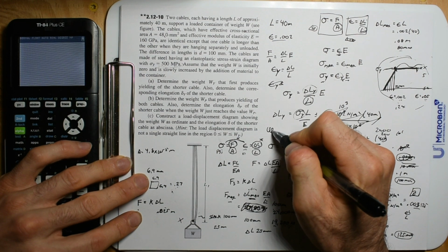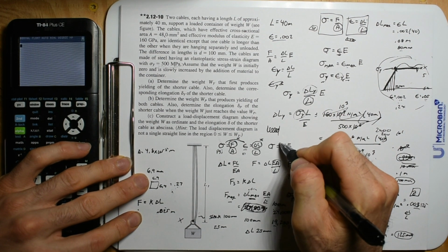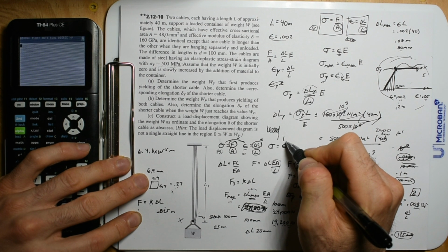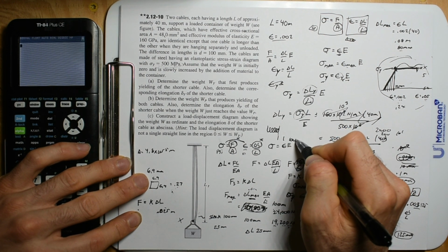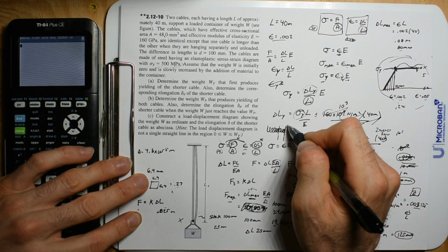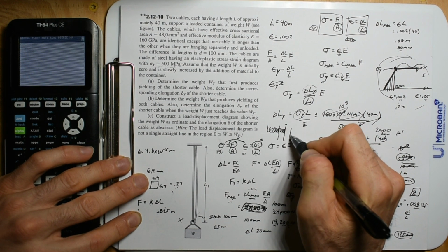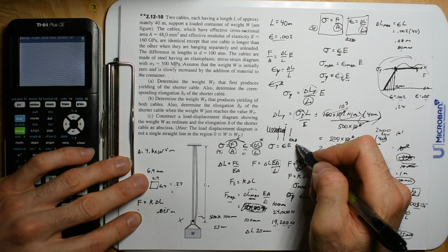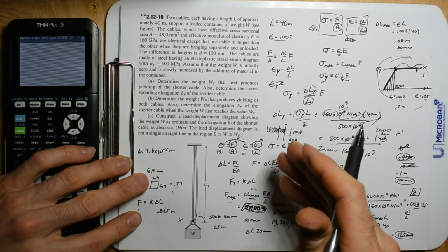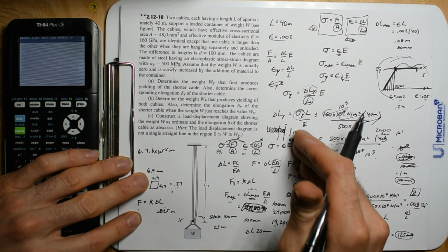If you have a spring that's unstressed and you move it an inch, let's say it takes 10 pounds. Well, let's say you come across a spring that's already stretched by 10 pounds and you want to stretch it another inch. Guess how much that's going to take? It's going to take another 10 pounds. Just that is not intuitive, though.